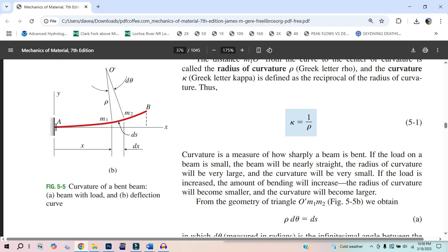And at point A, there is no deflection. And so it comes in nice and flat. And so there is no curvature either. And then at point B, you know what I mean, this is raised up. But check this out. If there is no curvature at A, but then B is ramped up at an angle, well, just think about it. The only way that would happen is if, one, you could have a sharp bend. You could go down this with no angle, get to here, and then make a sharp angle up. That's one way to get from A to B with an angle.